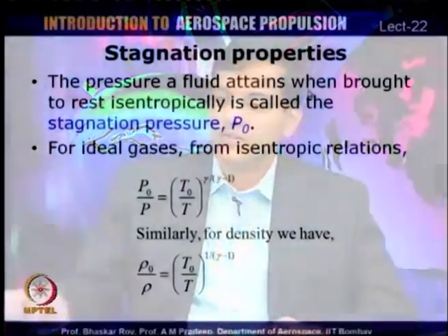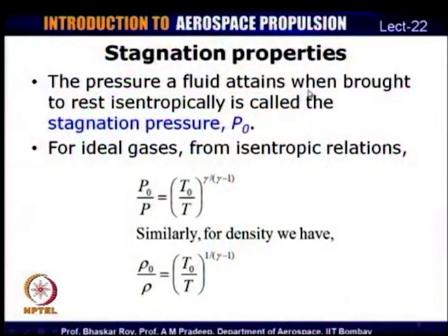So, stagnation pressure is equal to static pressure plus this dynamic pressure, and what we are trying to say here is that there are parameters which we need to take into account when the fluid velocities cannot be neglected. So, kinetic energy needs to be accounted for in calculating parameters. Similarly, the way we have defined it for temperature, we can also define stagnation pressure.